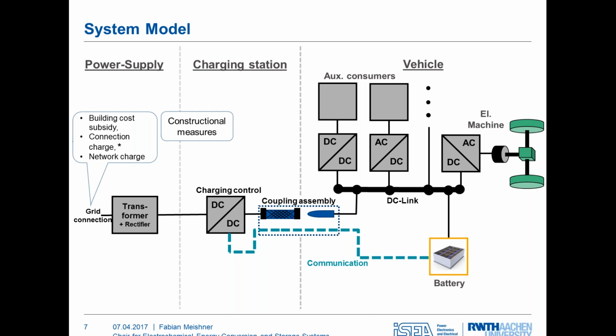And of course, our main interest is the battery in the vehicle, and also to estimate or have a look at how the battery is behaving under the operation conditions. Are there too high currents for the battery? Or how is the battery aging, behaving? Will the battery not live that long because it's cycled too much, or does it have a good lifetime in this operation? So really have a deep focus on the battery, and also different types of batteries and technologies, like having a fast charging battery with lithium titanate oxide, or having more slow charge iron phosphate batteries. So that's one thing we have a look at.